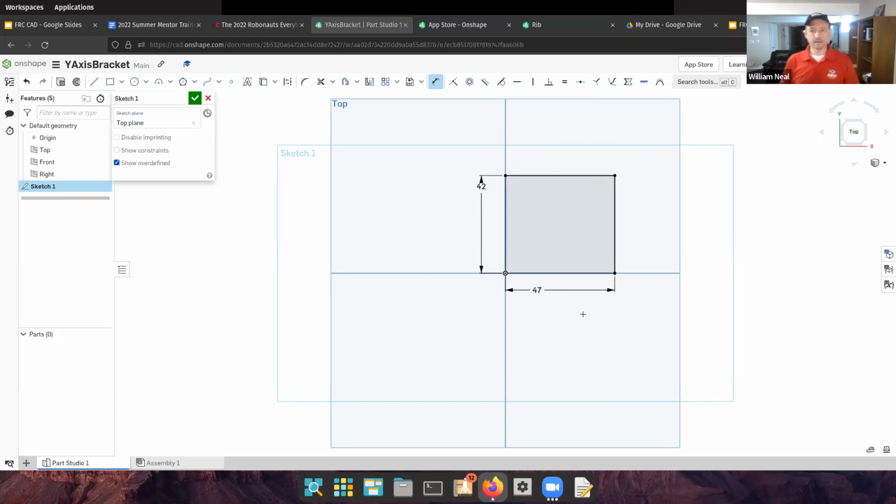Okay, that's my part so far. I'm going to put my motor mount here. So my 5 circles for my motor mount will go on here. So these will be a little familiar. And you see I'm drawing them rather quickly and not carefully enough to make them look all the same, because that doesn't really matter at the moment. And then I will do my constraints. So this one should be centered both vertically and horizontally.